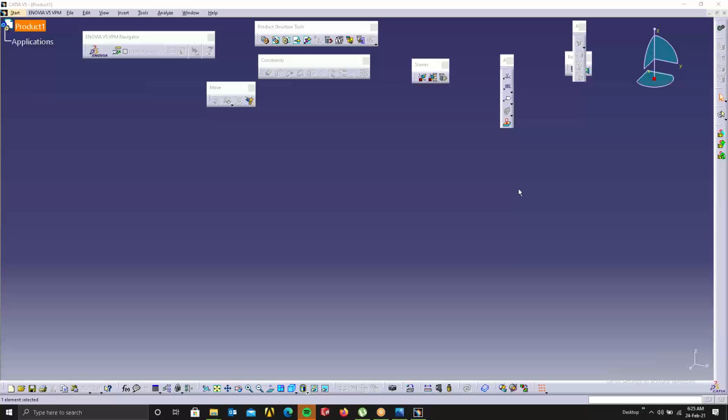What happens if we have not specified the flatness of the mating faces, the top face mating face and the bottom side of the top plate mating face? If flatness is not there, we won't get a proper braze joint. Then the whole product we have made is a total waste.